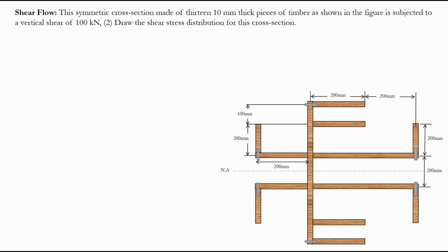The process is to divide our pieces so that we can calculate the moment of inertia of the whole cross section. Now we do know the moment of inertia of an individual rectangular cross section. So what we do again is to say that, okay, maybe this piece and the bottom piece, we can take them as a group, right? And calculate the moment of inertia about the neutral axis. And again, because this cross section is symmetric, we do not need to calculate the centroid of this cross section. So intuitively it's in the middle.